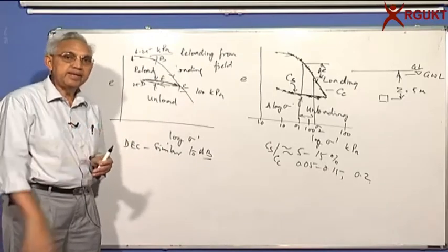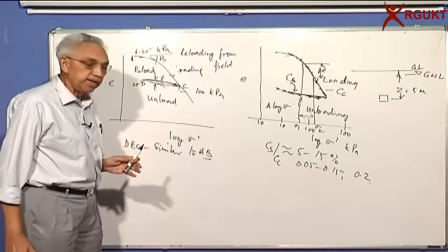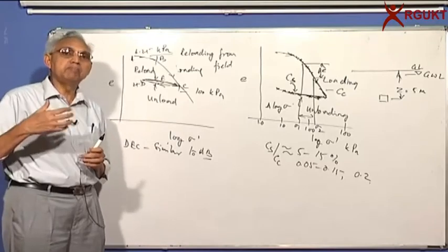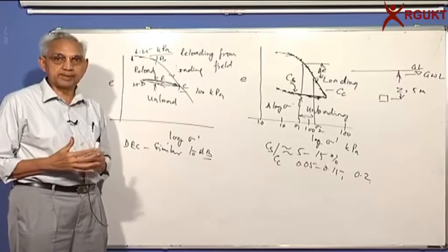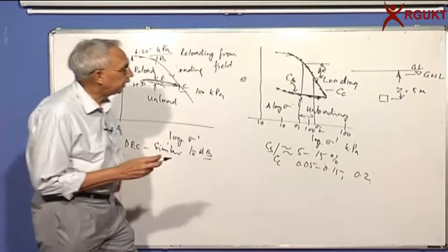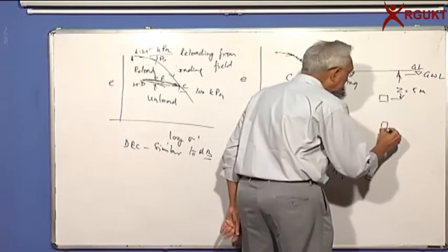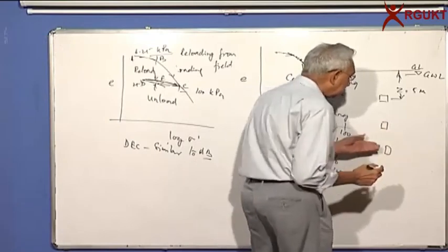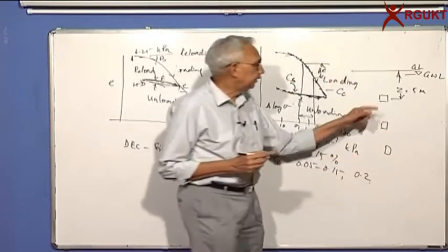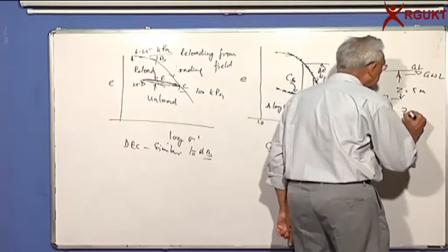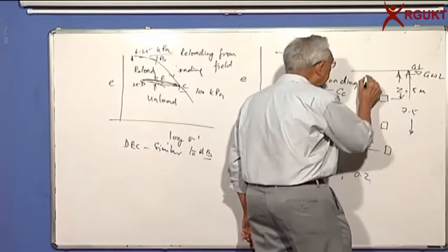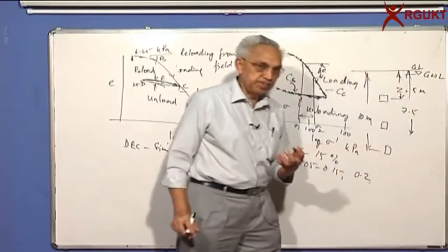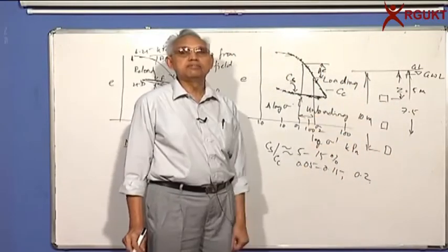That gives an idea. Is there a way in which I can find out what was the maximum stress the sample has experienced in the past? I don't know, maybe if I take a sample from 7 meters, 10 meters, the stresses will be different. This is 5 meters, say this is 7.5, and this sample is at 10 meters. So you agree that the initial stress varies for each of these samples.